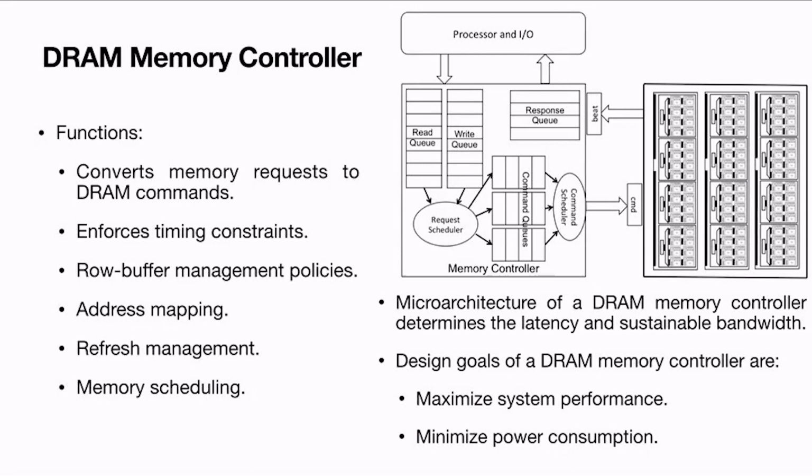Of course, when they decide on the memory controller, they also look at the underlying DIMMs, what DIMMs this particular memory controller is going to operate with, because the DIMMs are designed based on the JEDEC standard. JEDEC is a consortium which defines the standards for the DIMMs.